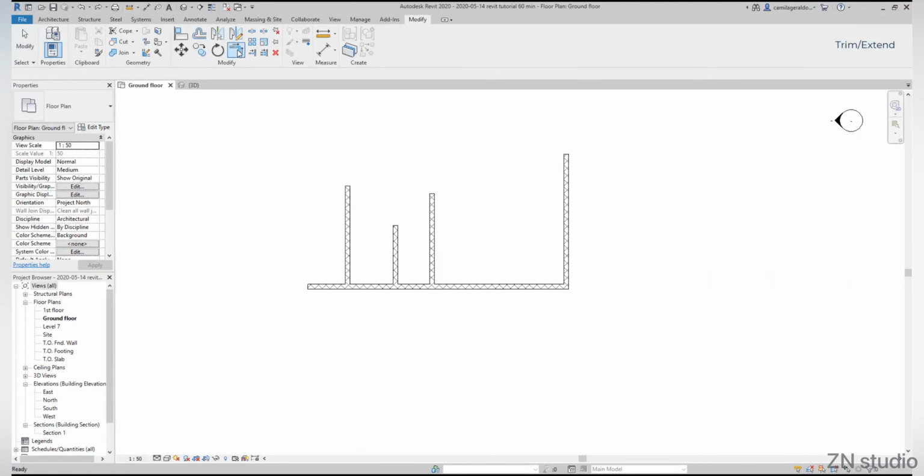You can also click on 2 walls that intersect to create a corner there. But why was the left side erased instead of the right side? Because it keeps the side that you clicked.